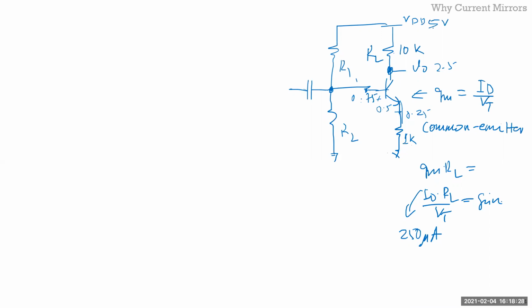It's actually almost close to a source follower, like I described before, because this resistor looks almost like a current source if it's a high value resistor. So this node will follow the source. If this node follows, then this current will be this divided by this, and that current times the RL resistor will give you gain. So instead of GM times RL, let's call this RE, your gain will actually be RL over RE. A lot of times we will use it that way. But if you want to make really high gain, then you want GM times RL because that's where you get the maximum buck for your current flowing through it.